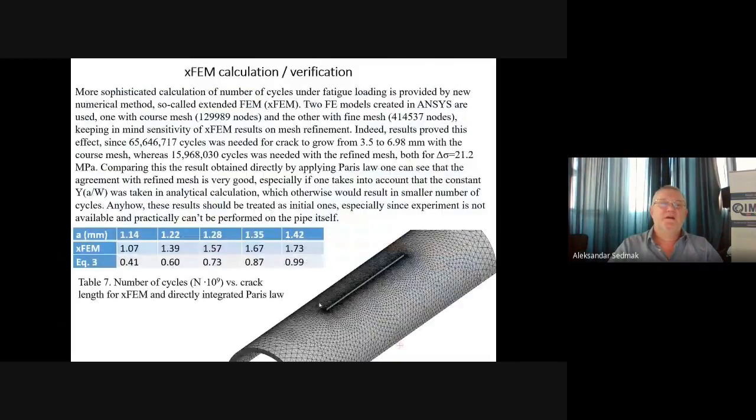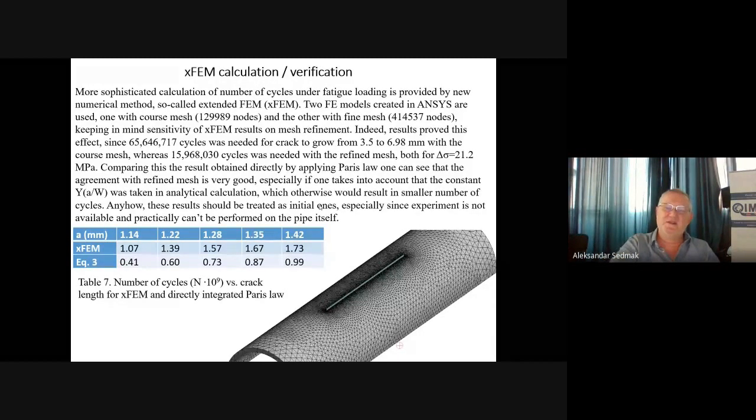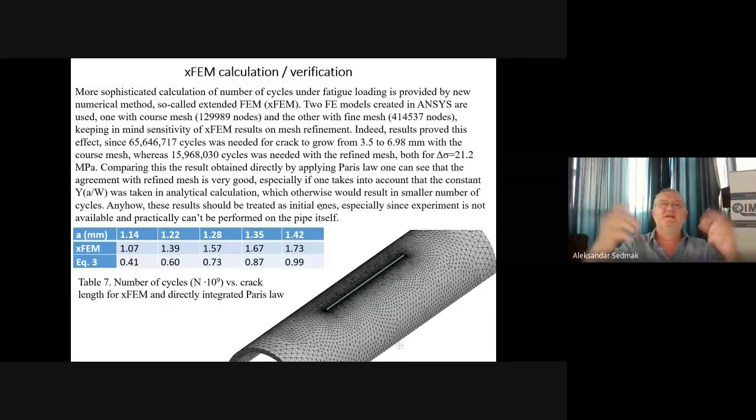Now, as I told you, it was a very simple way to do it, integration of Paris law for the crack that would grow into the depth. So cross-section and as if the length was all over the pressure vessel. But then again, we need some verification for that, and this is why we used XFEM.